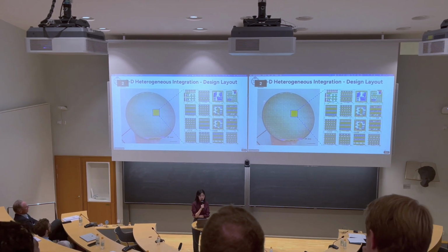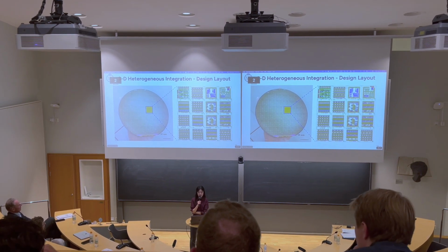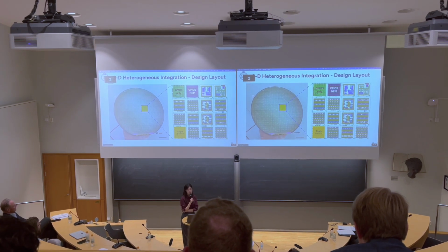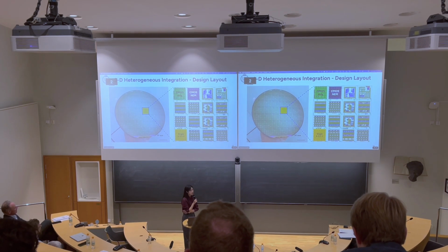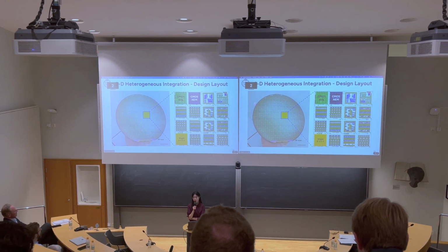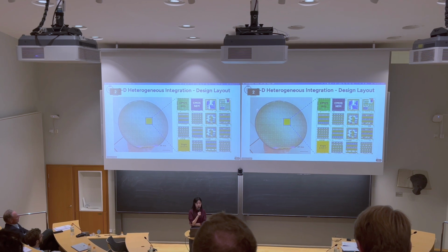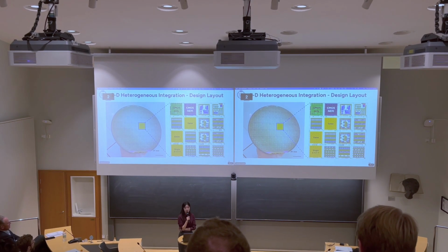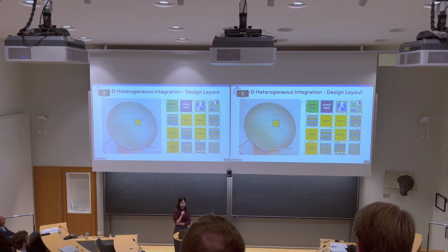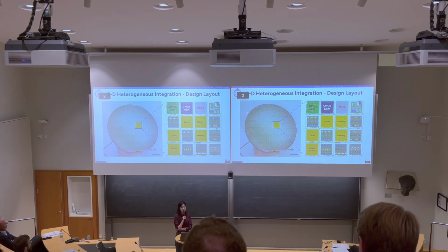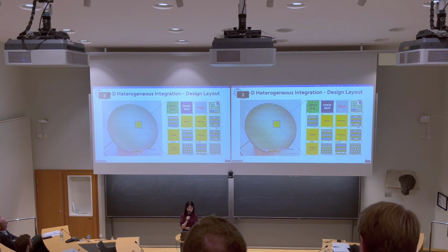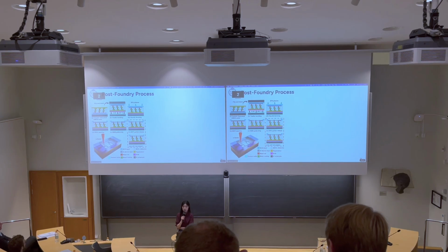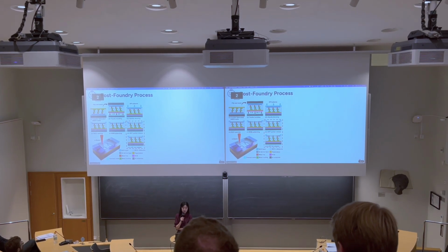So on these designs, first we have the switches that are built by pure CMOS, and then we also have the NEM CMOS hybrid circuits. And most of the circuits are built by pure NEM switches. For example, we have this simple 3T NEM cell, and we also have the logic gates and the memory cells. And finally, we also have a complete FPGA cell. So the rest of the foundry process is done on the 2 by 2 centimeter chips.